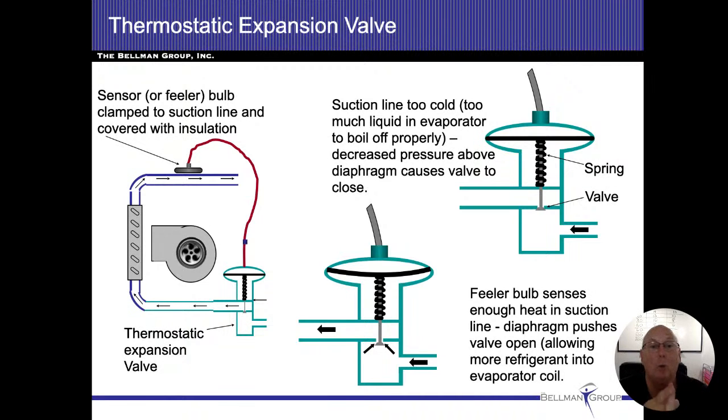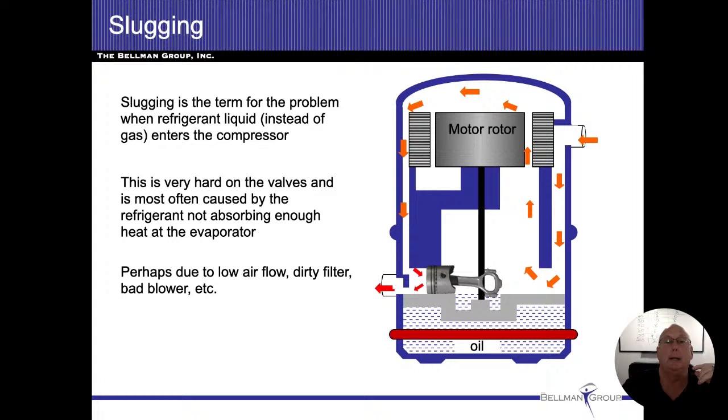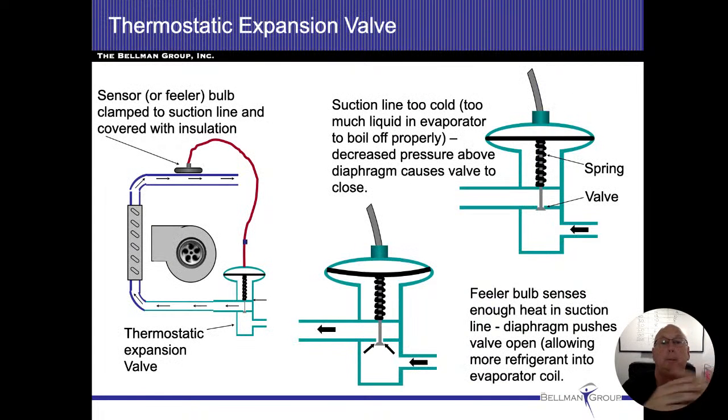I would like you to know the term TXV. I want you to know the term stands for thermal expansion valve. I realize this is a diagram on there, but that's basically what they look like. A little flying saucer type thing on the top, and then you'll see it located on the liquid line coming out of both ends.